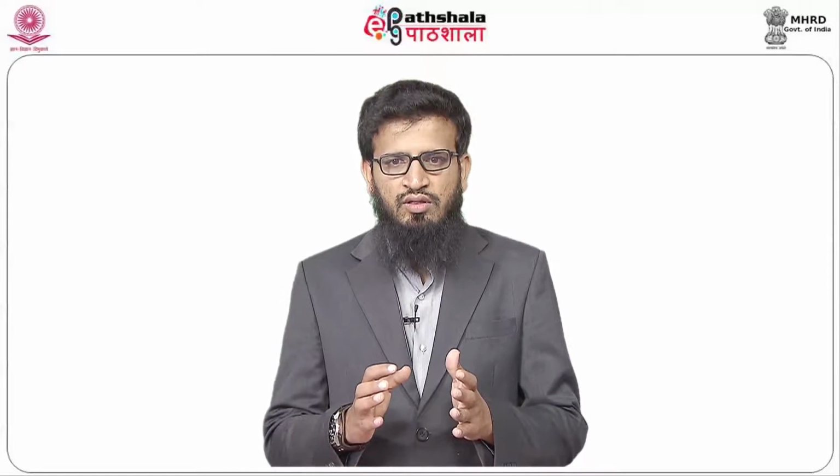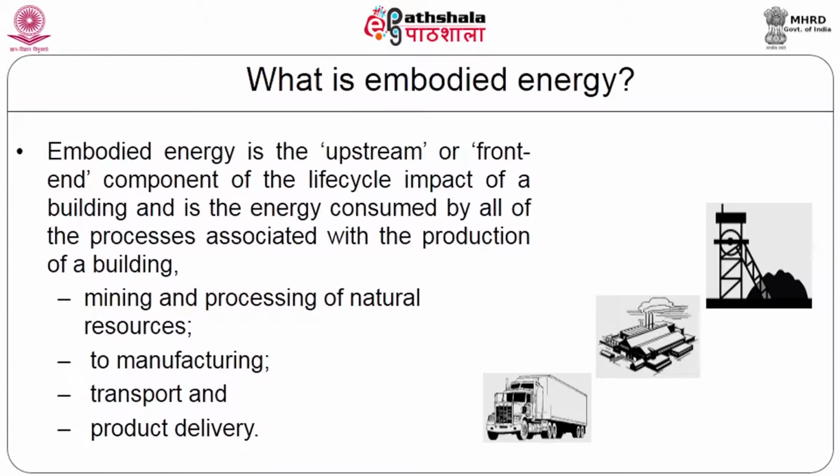Now, the way we will look at understanding embodied energy is in simple ways. What is it in a gist? It basically means that whatever material we are producing for construction, or whatever we get to the construction site, goes through a process. What is that process? For example, steel. It would require extraction of iron ore, that would be mining, then processing, then it goes to the manufacturing plant, gets the extrusions done, then transport and product delivery.